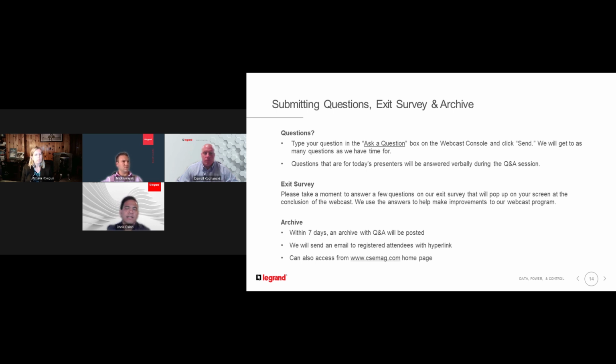Oh, I see. I got you. So it is the same tool from adding a circuit to removing it. If we're talking about the remote plug-in actuator, it goes both ways. You can rotate it in and engage your electrical conductors, but if you want to remove a circuit from the plug-in, you can use that same tool to disengage the conductors as well. So yes, it is in the pipeline, and it is the same tool as you would add a circuit. Great, thank you.